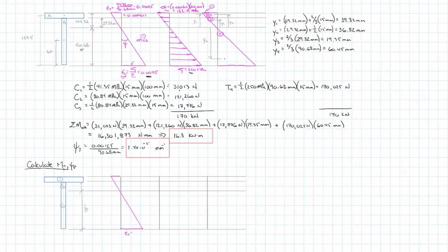And we're going to have our strain at rupture, 0.2, so considerably higher order of magnitude than before. And of course, it will arrive at that rupture strain at the bottom because the neutral axis is considerably higher.